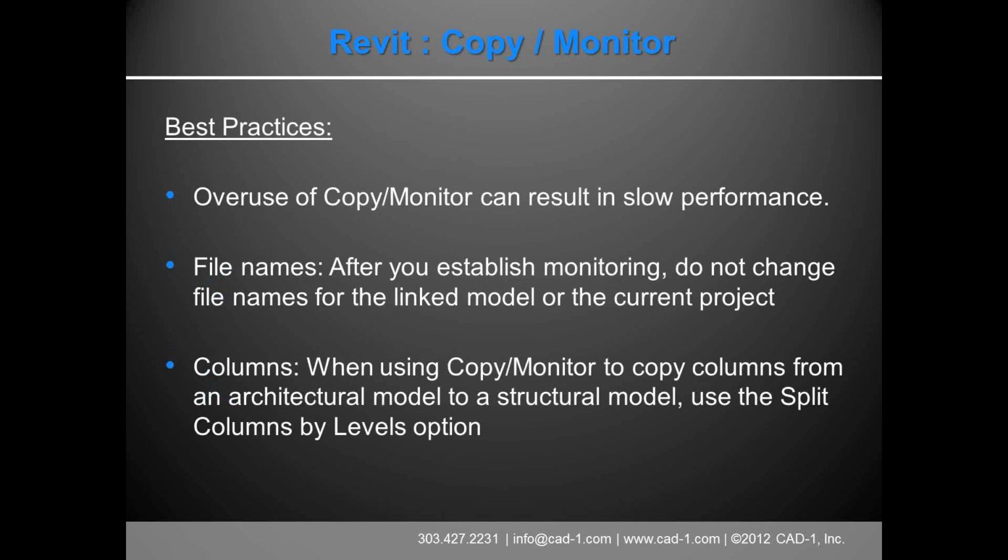Some best practices with this. Know that overuse, if you copy monitor too many things or just monitor too many things, can slow down Revit. So maybe you don't want to monitor every single wall, every single column, every single item. It can slow it down, especially on bigger projects.